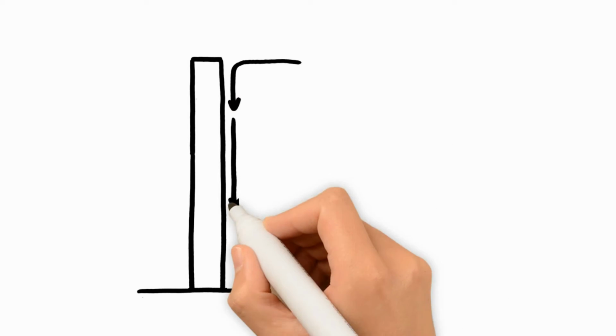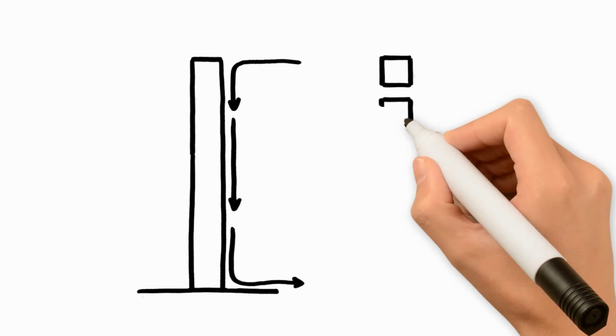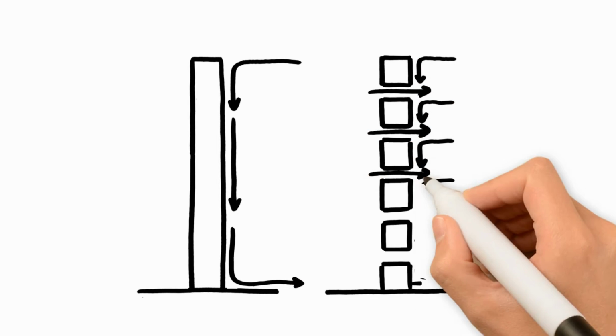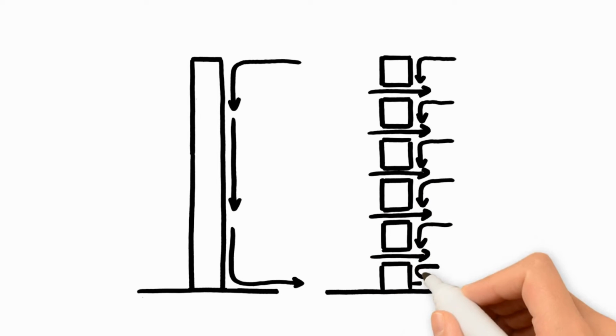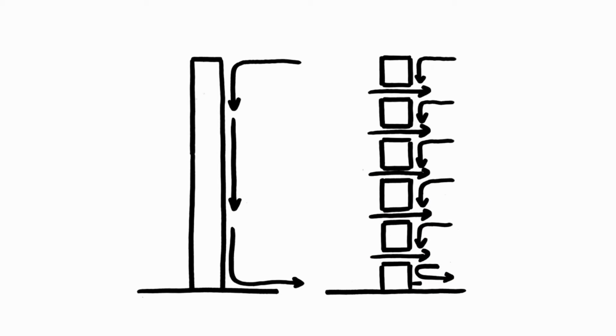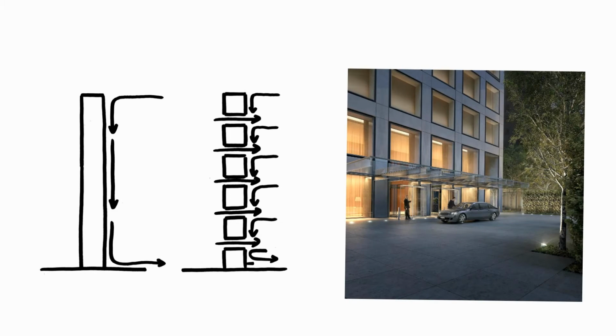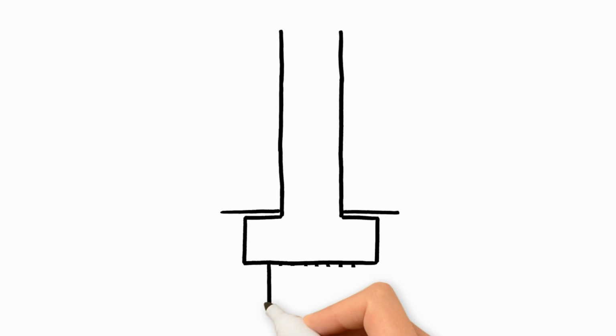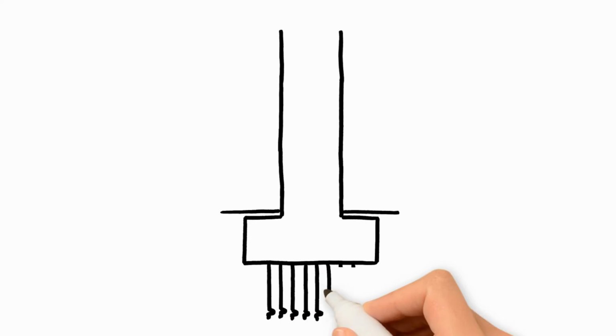When buildings are much higher than their surroundings, they can bring the fast-moving winds down to the ground level. This effect is known as downwash. The open surface stories help to reduce the effect of this by disrupting the flow. At the building entrances, there are small canopies that protect people entering the building from strong winds. The anchorage provides the foundation with movement resistance against lateral forces.